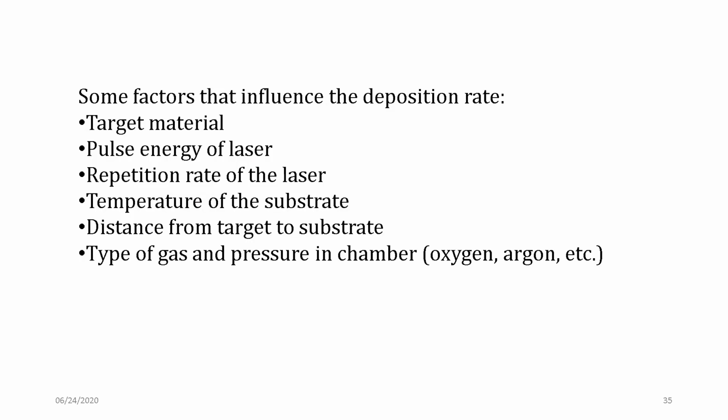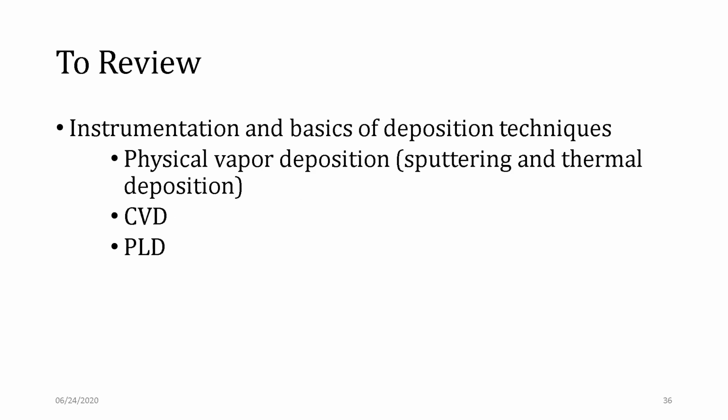Some of the factors that influence the deposition rate in PLD are your target material, the laser energy, the pulse rate or the repetition rate at which the pulses are sent, and then the temperature of the substrate. You can also vary the atmosphere inside. You can vary the temperature, you can vary the distance, and you can also vary the type of gas and kind of pressure inside the chamber. So to review, we have seen the instrumentation and little basics of the deposition systems to develop thin films.